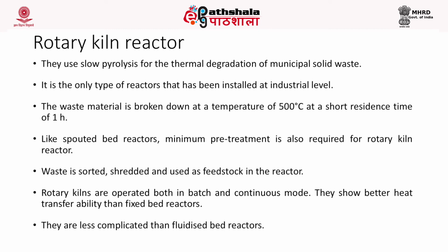Like the spouted bed reactors, minimum pre-treatment is also required for this type of reactor. That is, the waste should be sorted, shredded and used as a feedstock. Rotary kilns are operated both in batch as well as continuous process. They show better heat transfer ability when you compare it with the fixed bed reactors. Again, they are less complicated than your fluidized bed reactors.